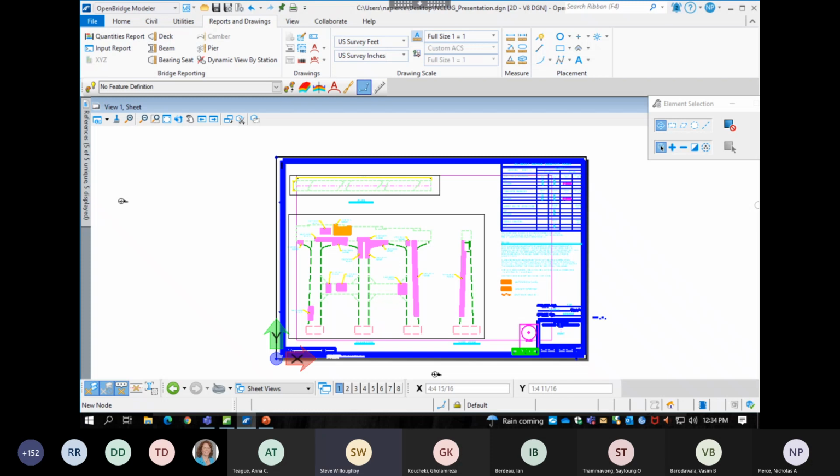If you wanted to get more detailed with the railing, that's probably where the ProSteel software would have to come into play to help you model anything steel related on your structure to a pretty high LOD. And then if it's done with that, these are MicroStation solids now, so they're going to show up in sections and in anything else you might need.